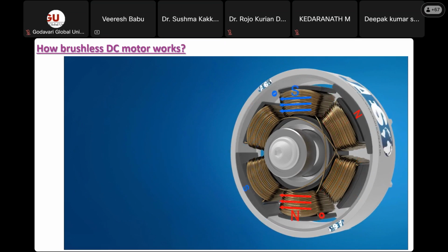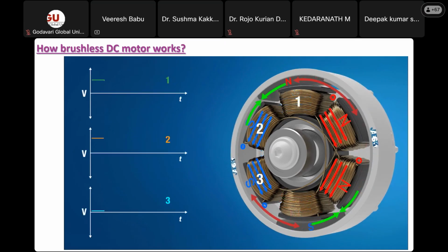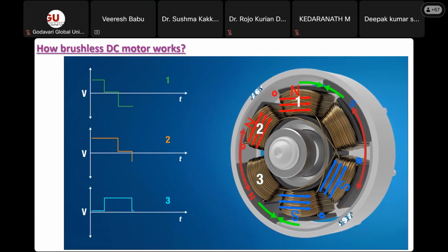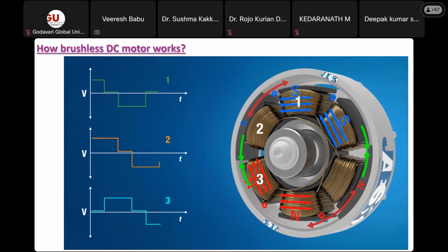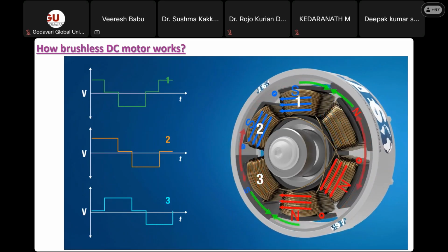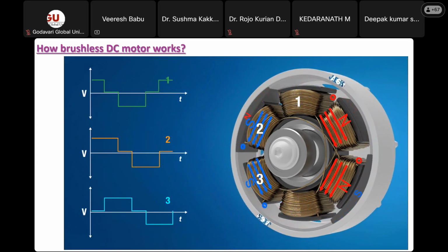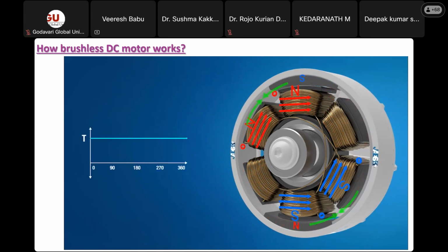In the case of more coils, always multiples of 2, it makes sense to use a sequence that uses them all, to increase the magnetic flux to which the permanent magnets are subjected and turning off only the opposite electromagnets. This simple foresight increases the torque, that is the power that the motor can supply, without substantially modifying its design criteria. The greater the number of coils, the smoother is the rotation of the rotor, which will thus have a constant torque.